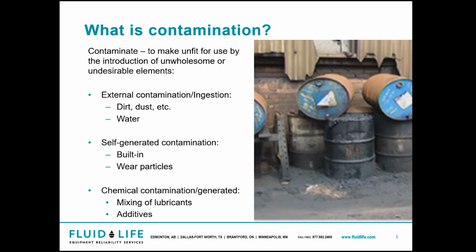We need the right viscosity package and the right additive packages. This is going to help maximize our oil life. This is also done by keeping the correct oil in the machine, keeping it clean, keeping it cool, and keeping it dry. What I mean is having a temperature controlled environment to store your oil. And like I said, most of our failures are going to be attributed to some form of contamination.